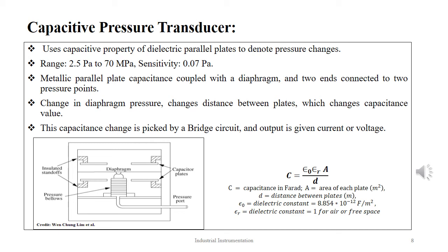The electrodes are attached to the diaphragm and are charged by a high frequency oscillator. The electrodes sense any movement in the diaphragm which causes changes in the capacitive value of the plates. This capacitance change is detected and determined by associated circuit components, and either voltage or current output is obtained, denoting the unknown pressure.